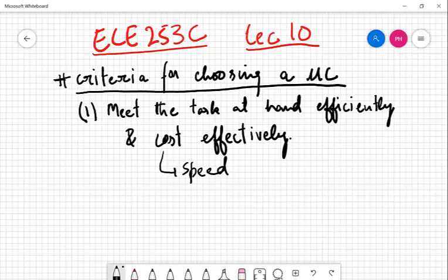As you may have seen, when you purchase a laptop, you see the processing speed, something like 1.6 gigahertz, 1.8 gigahertz. The same is true with microcontrollers. They run at lower speeds, at megahertz, like 16 megahertz, 20 megahertz, 40 megahertz. But before using a microcontroller, we have to see the maximum speed it supports, and whether this highest speed fulfills my needs or not.